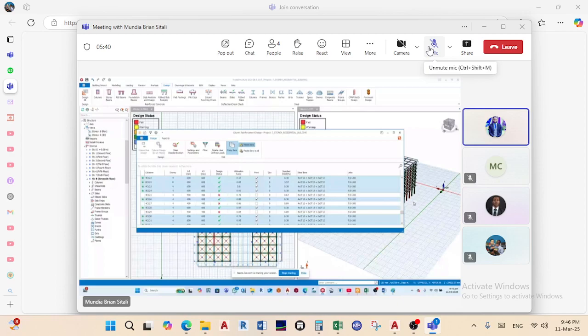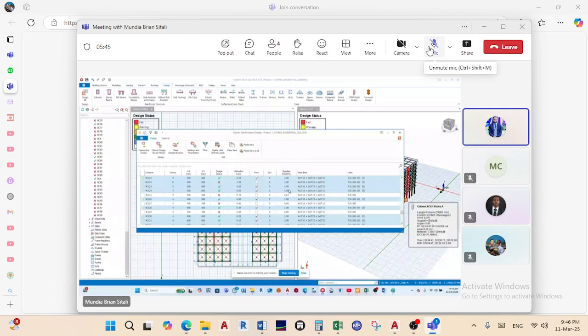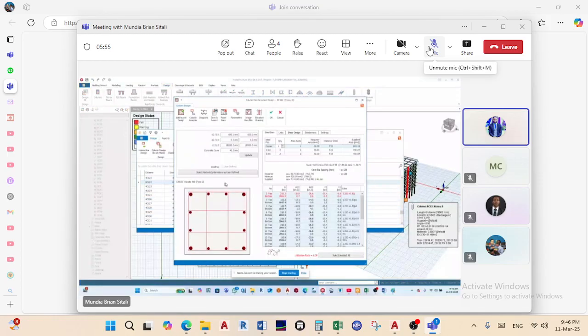Then even the ones that failed should essentially pass. So everything that I've edited where I put that should pass. Let me attempt to wait. So this one, I've done that, but it's still failing. So it's still at 1.0. So this column may be receiving a lot more loading compared to the others.